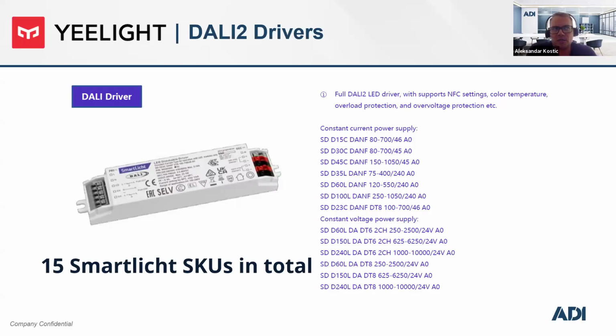Typically, constant current power supply is used for the spotlights, downlights, line lights, while the constant voltage power supply is typically used for LED tapes. So depending on the type of the lighting feature which we connect to the DALI ballast, we select one or the other.